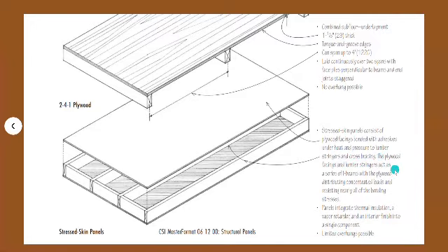The plywood facing and lumber stringers act as a series of I-beams, with the plywood distributing concentrated loads and resisting nearly all of the bending stresses. The panels integrate thermal insulation, vapor retarder, and interior finish into a single component, and limited overhangs are possible.